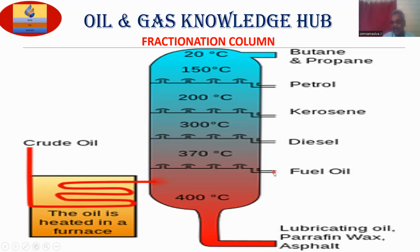Once it is traveling through this nozzle, it will be transferred. The first product is fuel oil, from the bottom. This will be transferred to the fin fan coolers, similarly to the storage tanks. If we go upwards, at 150 degrees Celsius, petrol will come. Through the downcomer, it will draw and transfer to the fin fan coolers. From the fin fan coolers, it will go to the storage tanks.